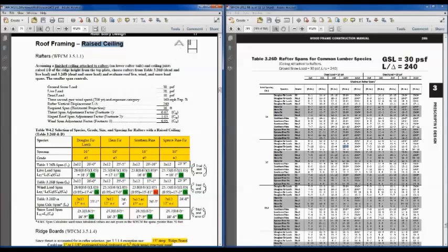And so this is the vaulted ceiling over the bedroom, and this is also a finished ceiling. But in this case, the rafter tie is up a third of the ridge height from the top plate. Okay, so what's going to be different about this particular example? Everything is going to be the same, except this thrust span adjustment factor, footnote 1.